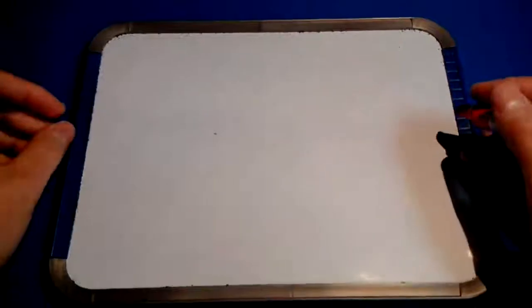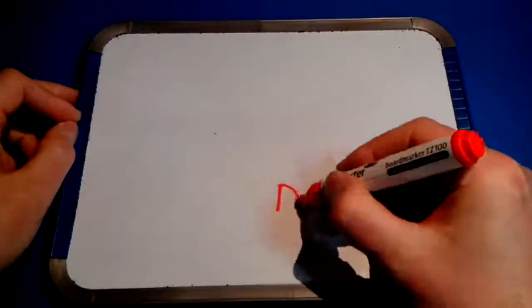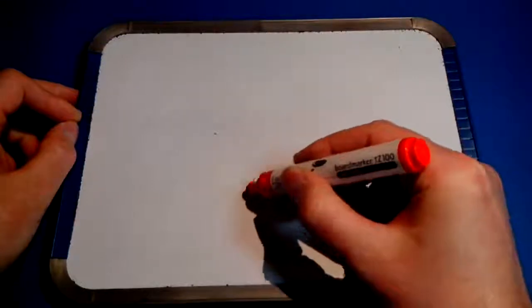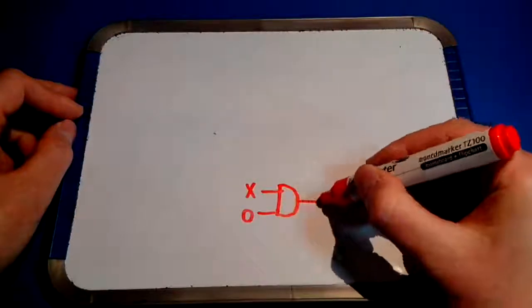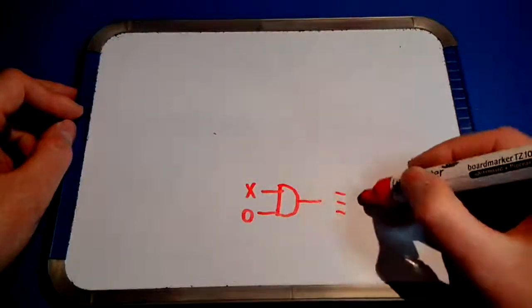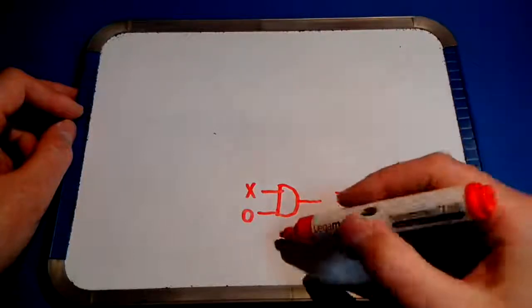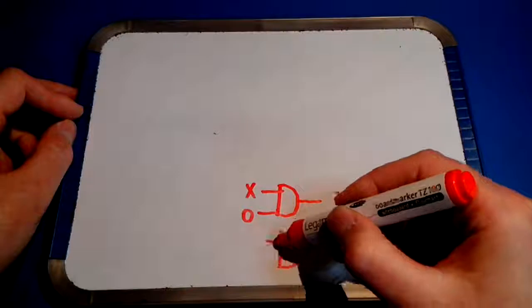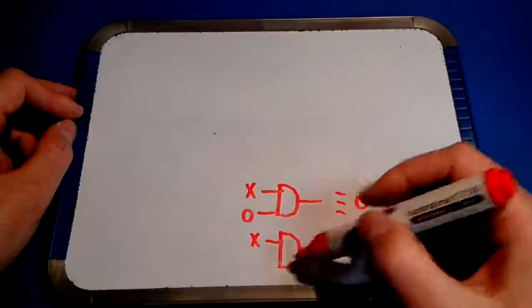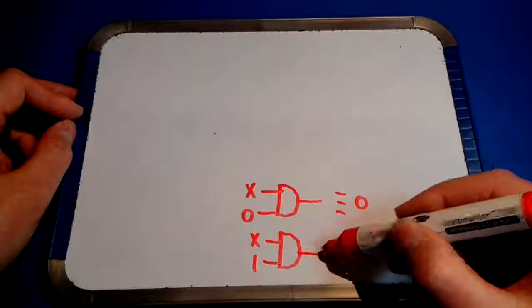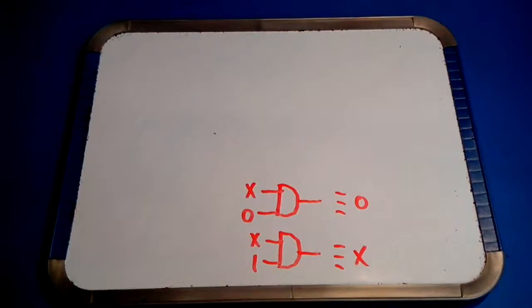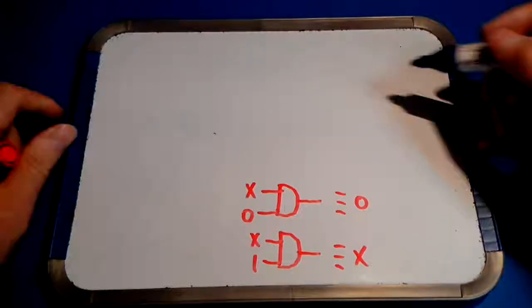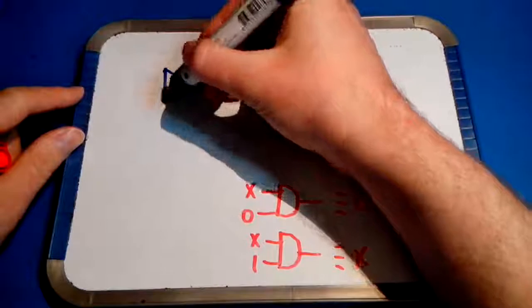Now, when making a 1-bit multiplexer out of gates, let's remember that if you have this AND gate, you connect some value to one input and connect a fixed 0 or false to another input, the output is always 0 or false. Furthermore, if you have this AND gate, connect the same value X to one of the inputs and a fixed 1 to the other input, the output value is always X. With this in mind, the 1-bit multiplexer can be made like this.